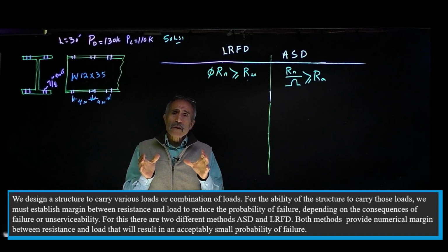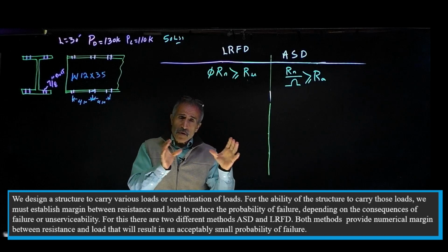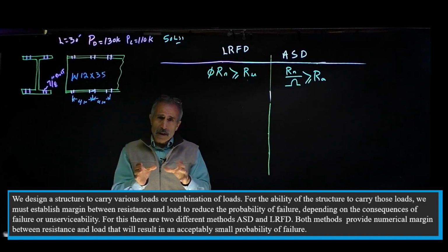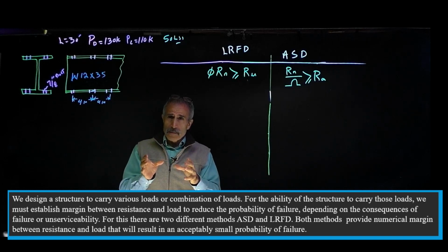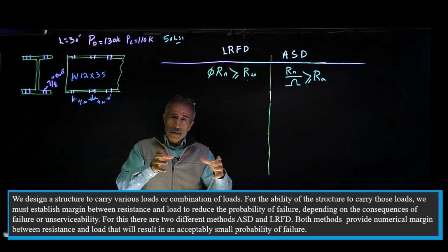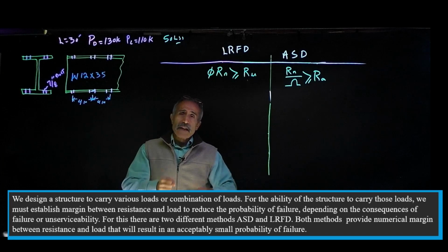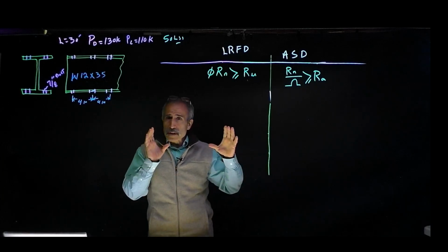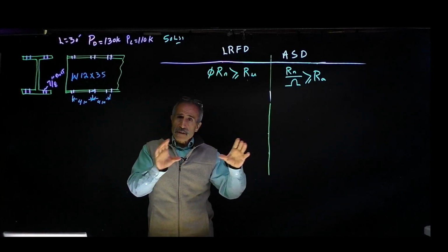But both methods use some type of numerical margin between the resistance of the material, the capacity of the member, and the applied load. Both use the same margin, but they have different ways of applying it.